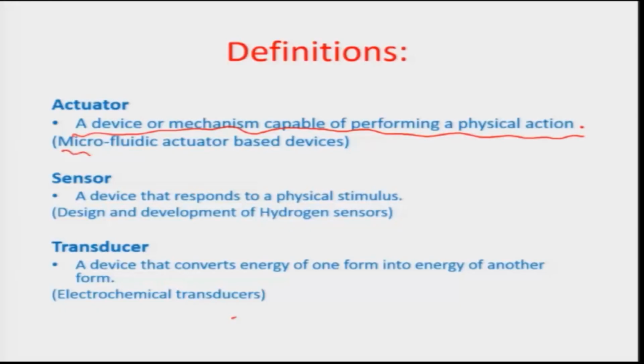Similarly, there can be initiation of a few membranes, because of which a travelling contractile effect is created, and it leads to an increase in the flow velocity. So, these can again be actuators. Such actuators are used in unison for many purposes, and one of the very critical purposes is controlling and defining the flow behavior at the microscopic length scale. This whole area is known as microfluidics, and there are several actuators designed based on different device technologies for assisting the flow at the microscopic length scale.